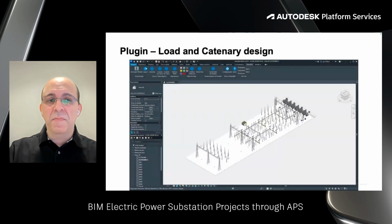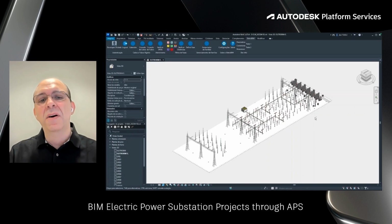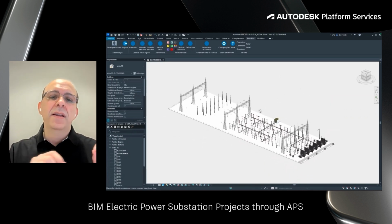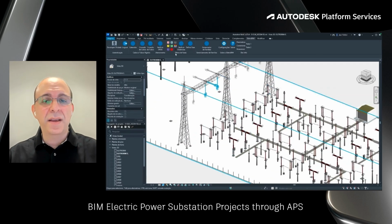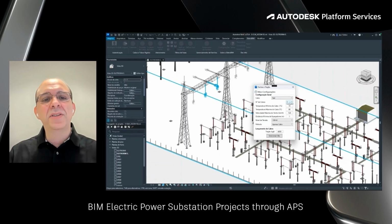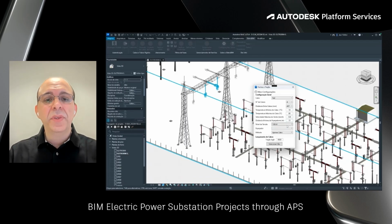Another aspect of this, as I mentioned, is to bring engineering calculation. So we have this thing that we call catenary design. Essentially you have the span, the distance, you consider the cable type, cable diameter, temperature variations, and all those things, they are considered to design a perfect curvature. And as you can see in this input information, you define the number of cables, the temperature that is going to be predicted in this portion, and the voltage that also impacts the design.